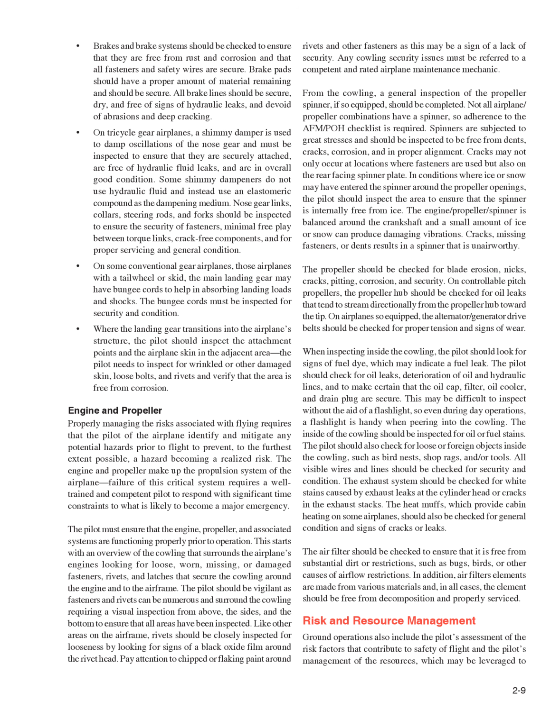The air filter should be checked to ensure that it is free from substantial dirt or restrictions, such as bugs, birds, or other causes of airflow restrictions. In addition, air filter elements are made from various materials and, in all cases, the element should be free from decomposition and properly serviced.